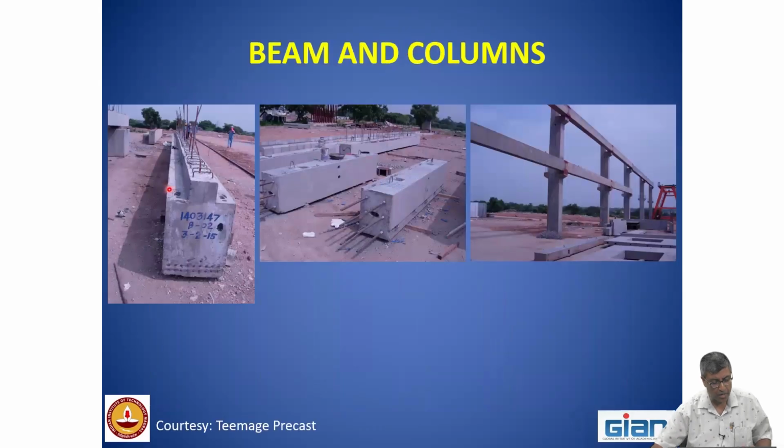Now this is a photograph from the factory I visited in Tirupur. Here you can see these are the ledges. Over that are the shear connectors, and when they put the hollow core slabs, they will have a structural topping where the beam and the slab will get integrated. They were actually extending their factory with their own products. That was nice to see, how they are using their products to construct their factory.